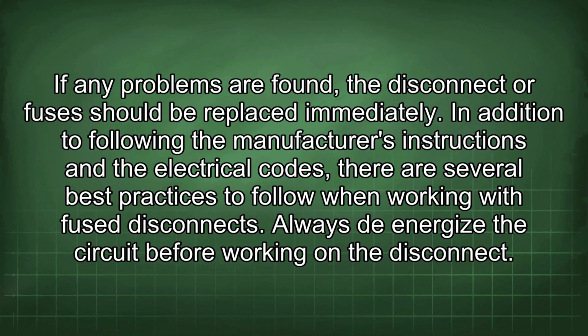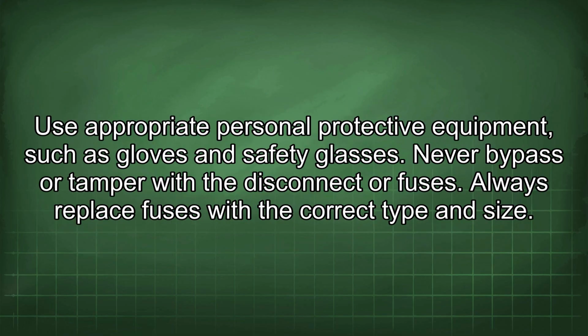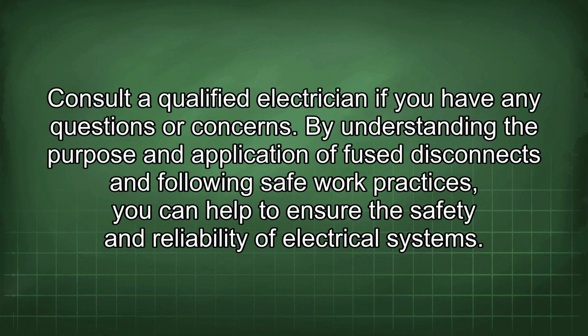In addition to following the manufacturer's instructions and the electrical codes, there are several best practices to follow when working with fuse disconnects. Always de-energize the circuit before working on the disconnect. Use appropriate personal protective equipment, such as gloves and safety glasses. Never bypass or tamper with the disconnect or fuses. Always replace fuses with the correct type and size. Consult a qualified electrician if you have any questions or concerns.